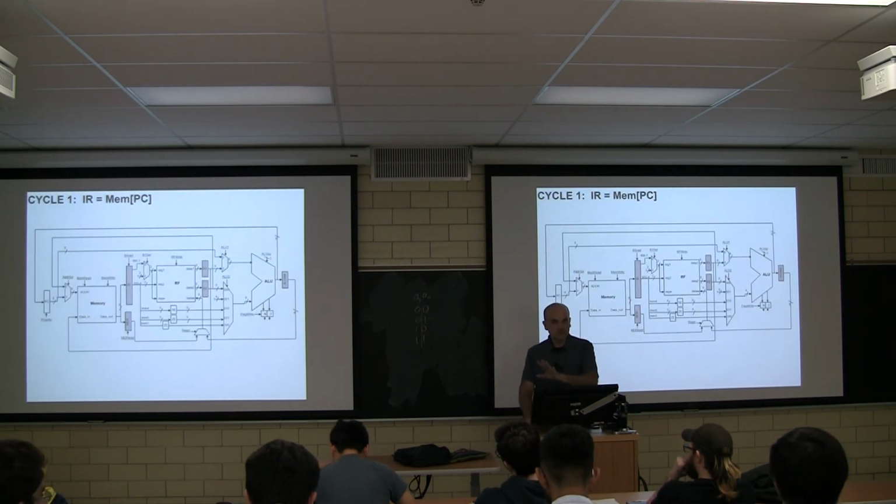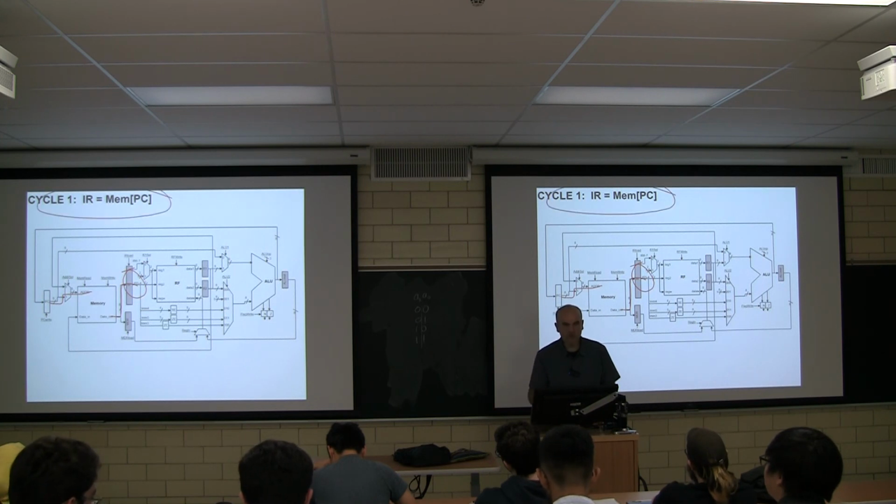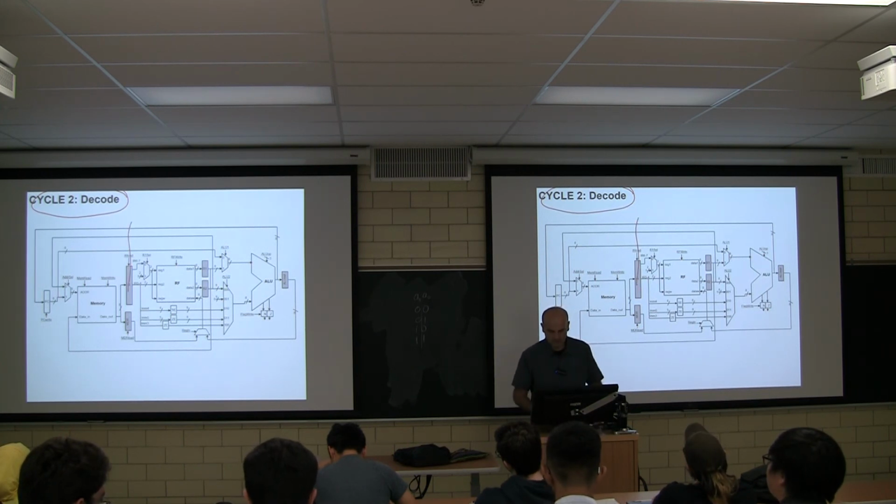Let's do this again. Sorry, very quickly, and I'll explain what's going on. It's a way to show you what else we need to do. So first clock cycle, let's read the PC and send it as an instruction, and we'll load into IR. That's cycle number 1 according to what I'm showing over here. This is not going to be an optimized implementation. Cycle 2, decode. Let's not read the registers yet. So we're looking at this and the control is deciding what to do.